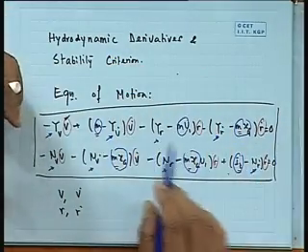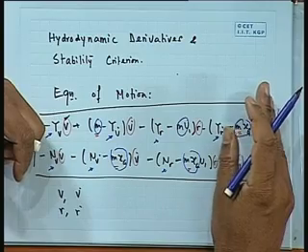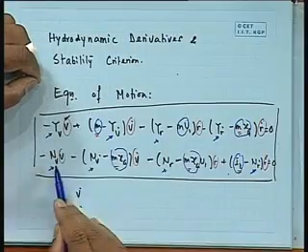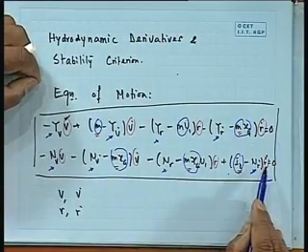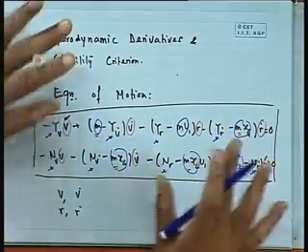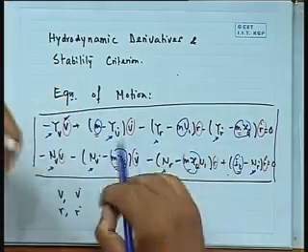You see, if we can find the solution for that equation, we may not be able to find the exact numerical value, but the nature of the solution would tell me if the shape is going to be stable or unstable. How? Because it has something into v, something v dot, something r dot. This is what is known as a set of linear differential equations. Now, if you can tell how v and r change with time, that tells me whether the shape is going to be stable or unstable.